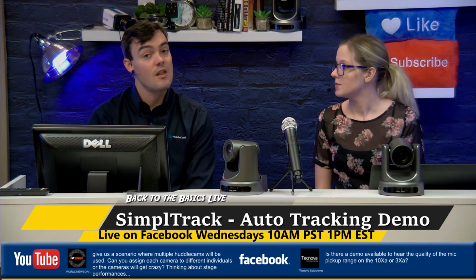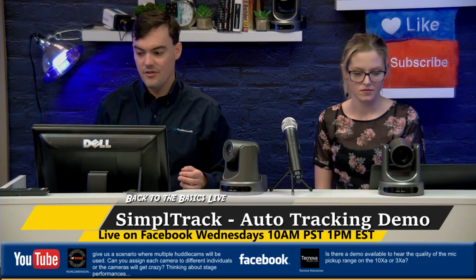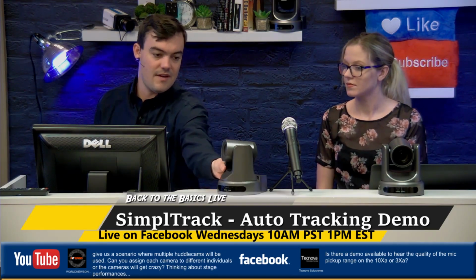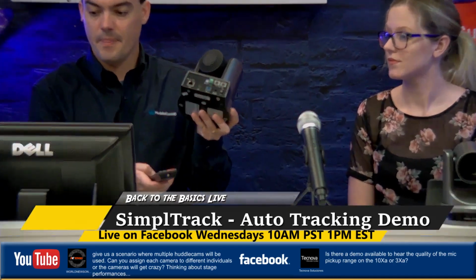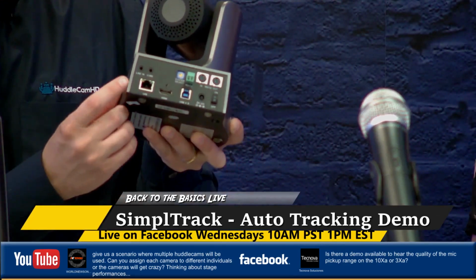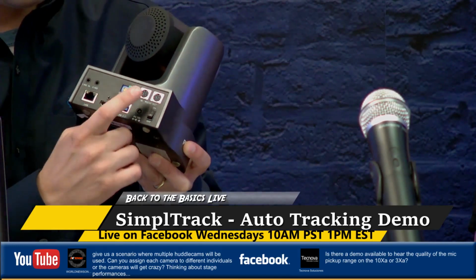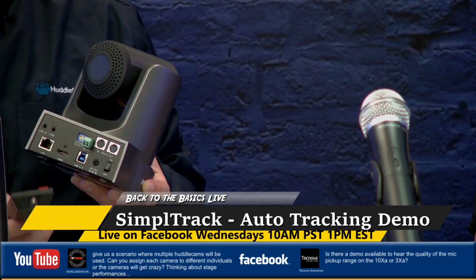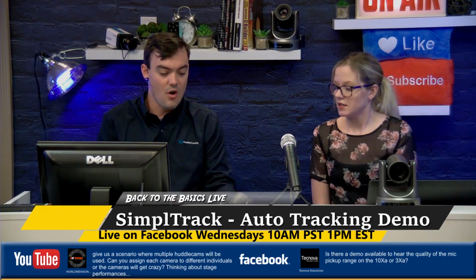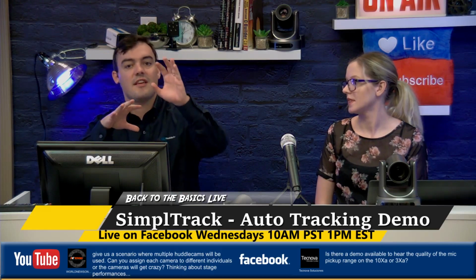Now, in that scenario, one of the good things that you can do is daisy chain the controls of the cameras. In fact, I just noticed we've got this camera here, and you can see on the back that it has RS-232 in and out. And every HuddleCam has RS-232 in and out. So you could connect the joystick to the first one, and then have the second one connect to the third, and the third to the fourth. And control them all from a single joystick. So that's convenient. It's kind of like having a master controller where you go, camera 1, move it over here. Camera 2, move it over here. And then you have somebody changing the cameras from left to right.